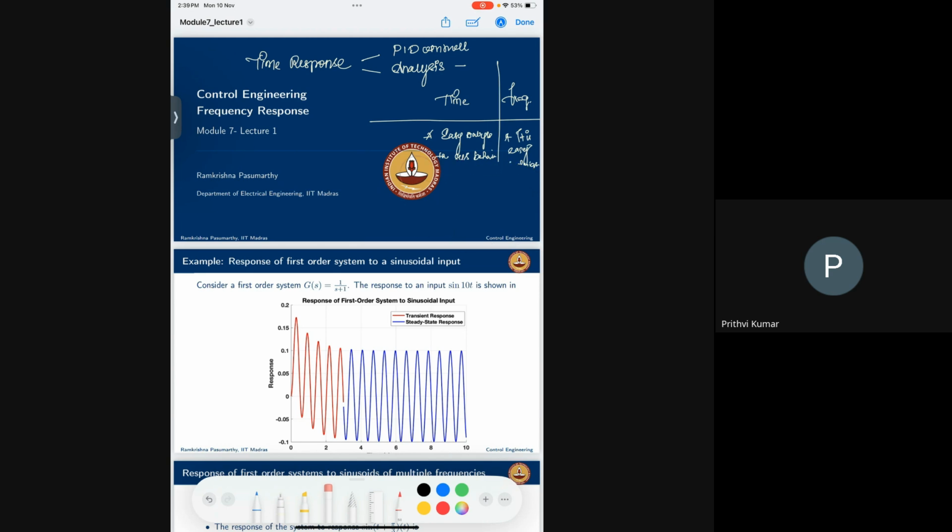And the representation of the system is very easy when compared to time domain. In frequency domain, when representing a system and doing an operation, everything will be a multiplication, not convolution or any other things. So when in time domain we do convolution, in frequency domain we just do multiplication. It will be easy to compute, and the resources required on any computer or PC will be less. Instead of spending so many resources on convolution, I can straight away do a multiplication and get things out. So these are several advantages of using the frequency domain.